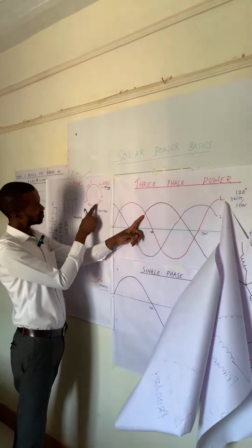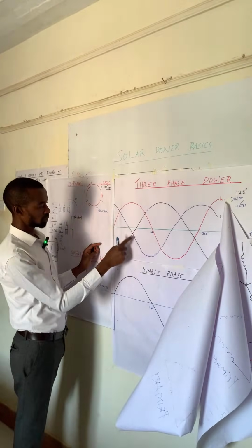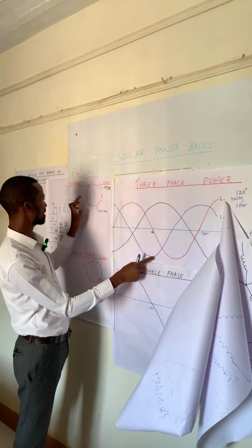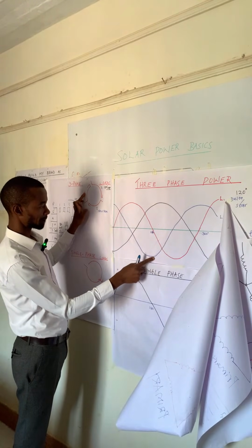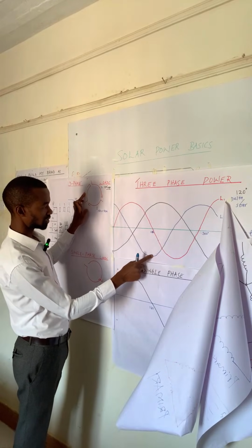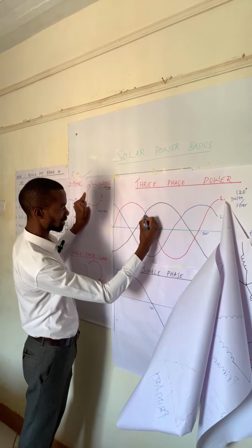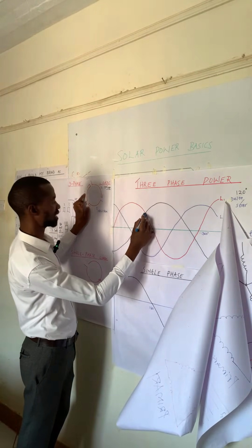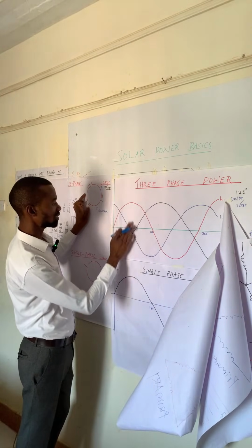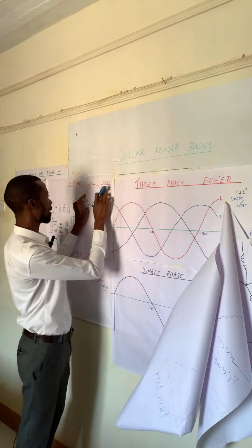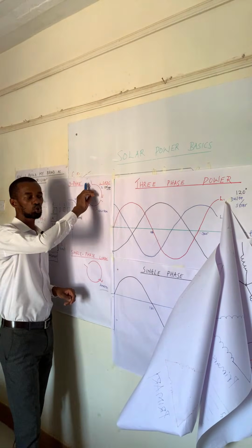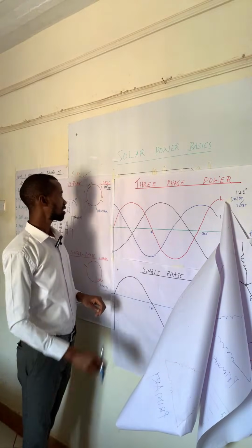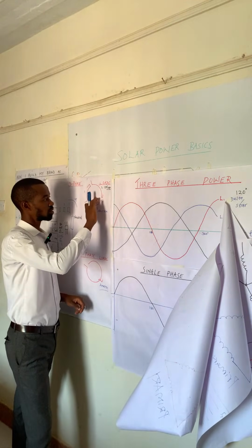And then when it turns to this point number 3, we could be at this point here. And then that means that at this point, we also have some current that is flowing. Remember, this one will be meeting at this point. So that is 1 and 2. As 1 is going down, 2 is going up, and therefore it will ensure continuous rotation of that motor.